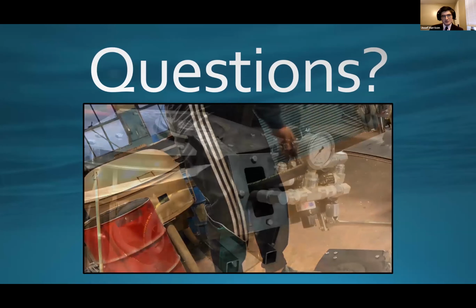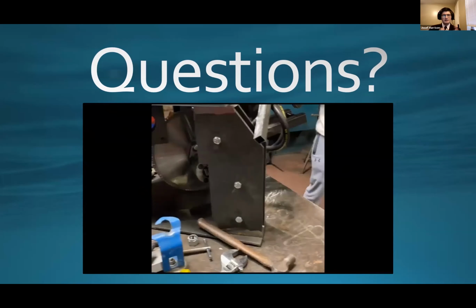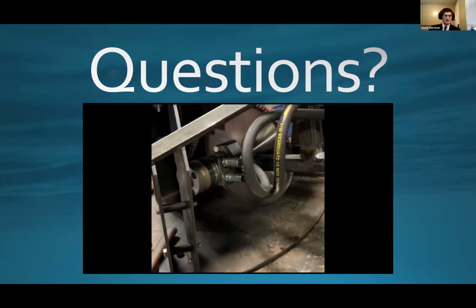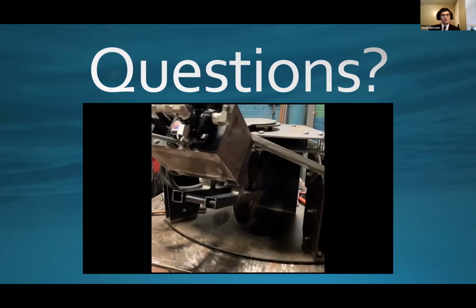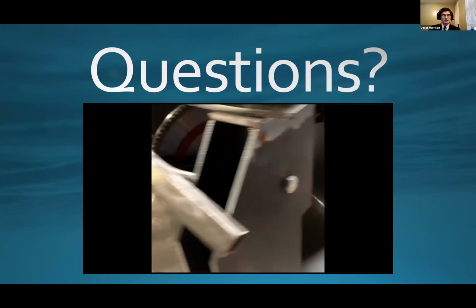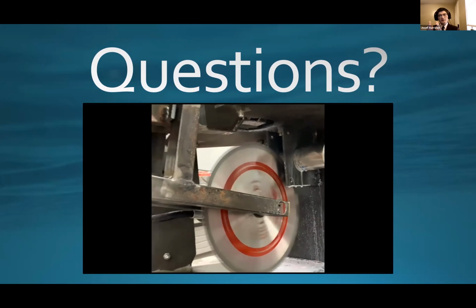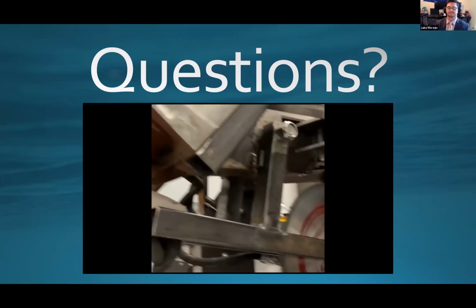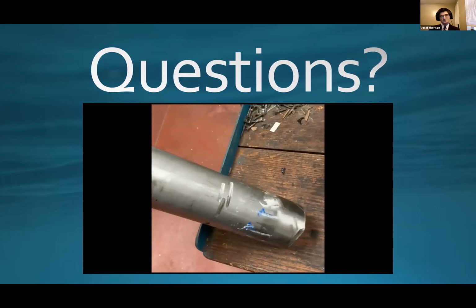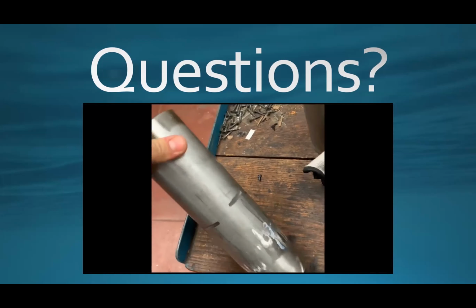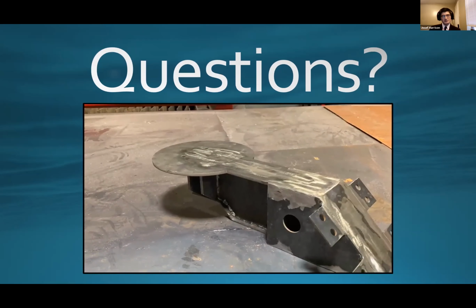In order to shear the lead screw, we would have needed to put a truly astronomical amount of pressure on it. I don't have those calculations memorized, but we also determined that to shear through Inconel, the only material we had access to budget-wise was steel, and the bulk of steel required to survive shearing Inconel would have been more than can fit between the Inconel bolt and the clamping mechanism. Only about a 2-inch space. We would have needed a great deal of steel behind it as well to support the shearing process. Understood. I might show that in your report, since shears are used a lot in this industry for things of that depth.